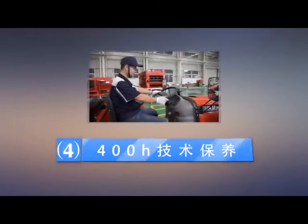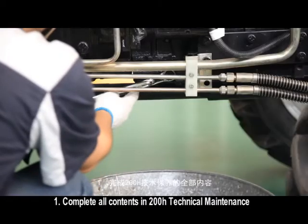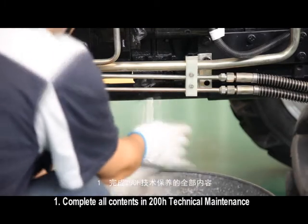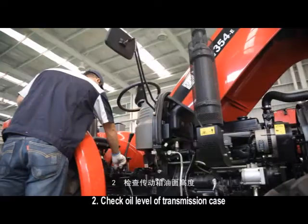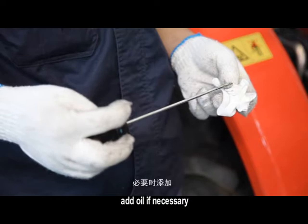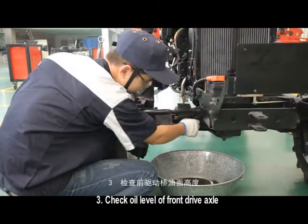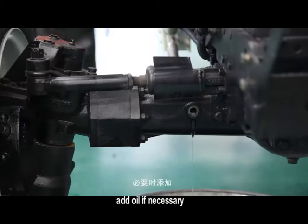4. 400-hour technical maintenance. 1. Complete all contents in 200-hour technical maintenance. 2. Check oil level of the transmission case. Add oil if necessary. 3. Check oil level of the front drive axle. Add oil if necessary.